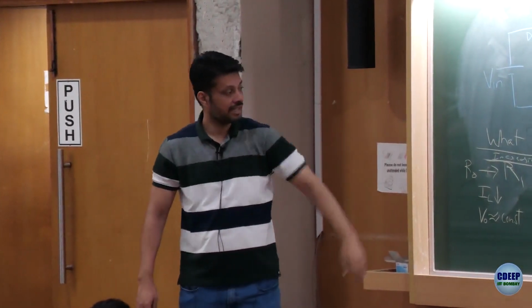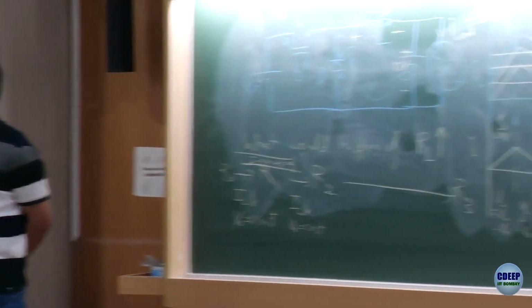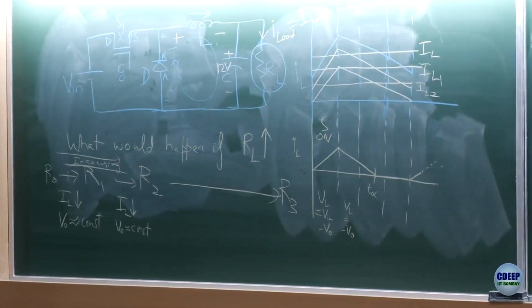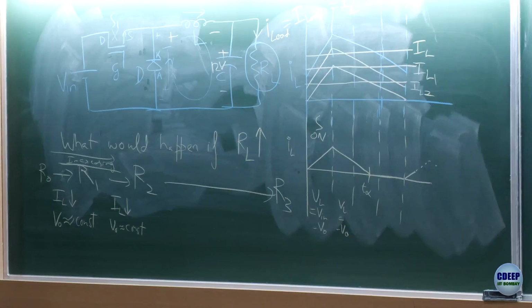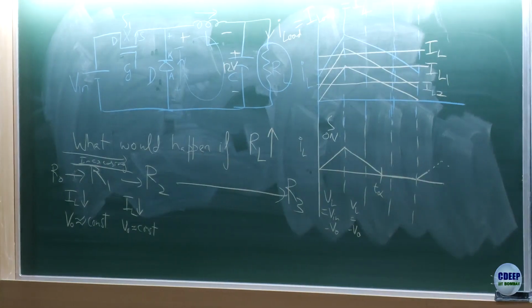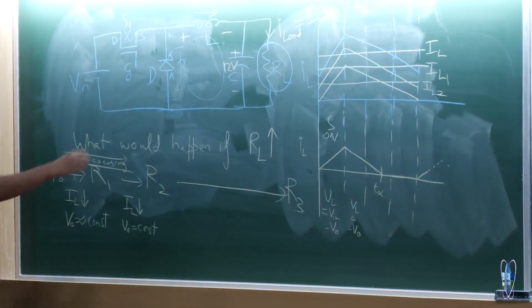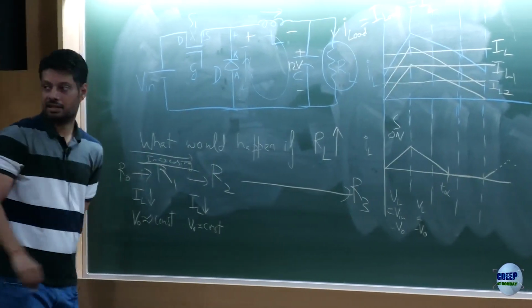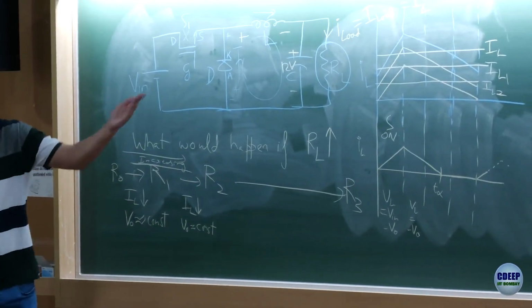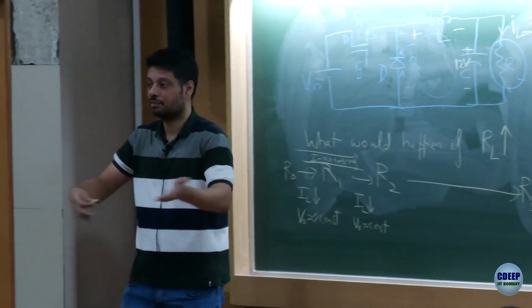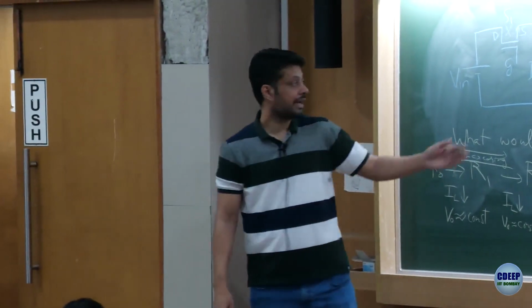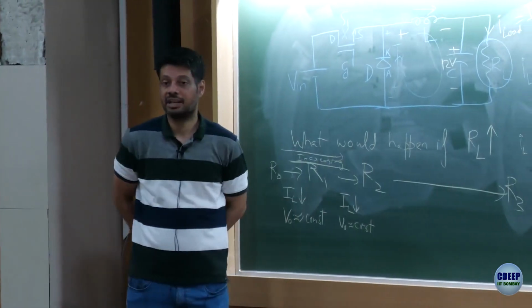So this is how the inductor current would look like. It will not go negative, it will never go negative. It will only remain positive. Because this diode cannot allow negative current, right? As simple as that. If you had an ideal switch, current can be positive, current can be negative, anything is fine. The diode would never allow a current to go in the negative direction.